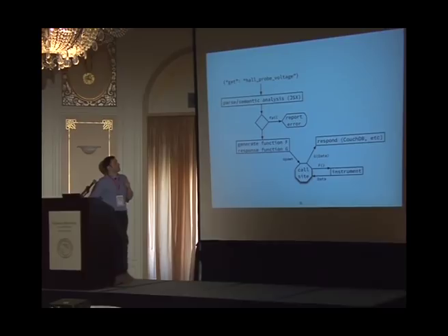So I apologize for the wall of text, but I think it's interesting to look at an example. I showed you the sort of disgusting string that has to be sent to an instrument in order to get it to read a value. But what's important to recognize is that even though there are these big strings that need to be sent, in general, there's a very consistent behavior. There's a very consistent interface to hardware. You have a bus. It may be Ethernet. It may be GPIB. It may be something entirely different. But what you do know is that the instrument wants a certain string, or a certain sequence of bits, or whatever. So the instrument modules themselves actually do no communication with the hardware. They only tell the bus modules what strings are supposed to be sent.